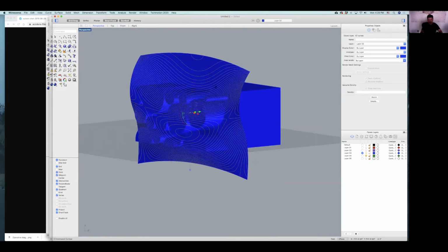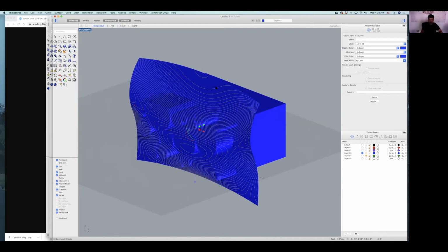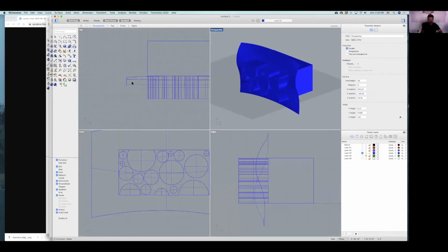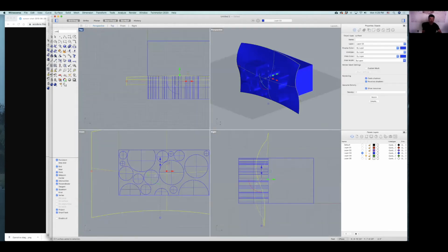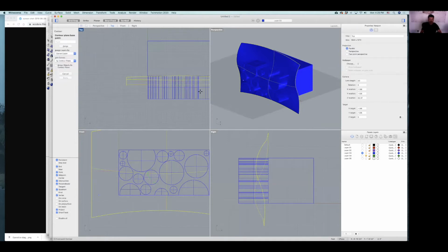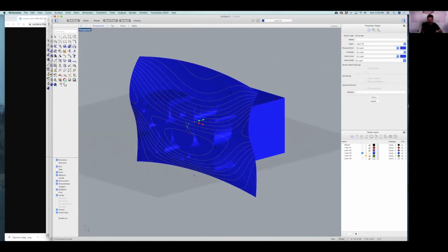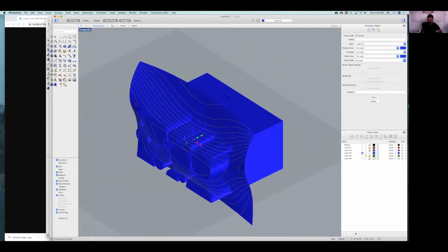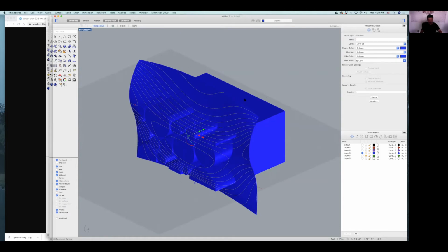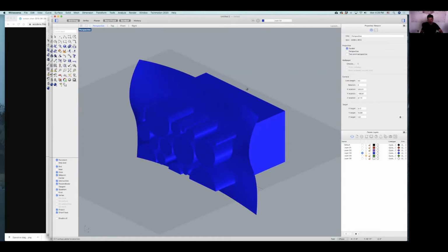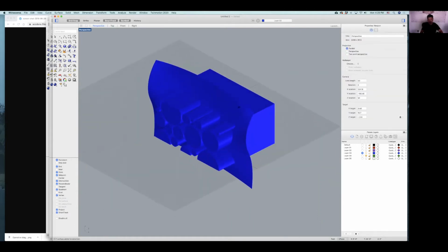I think this line is a little bit too fine, so I'm going to change it to something like 6 inches. So contour, click here, and type 6 inches. That's going to give us this kind of topography line over the surface, which is useful. I'm just going to group it, so it's going to be shown when we make 2D.